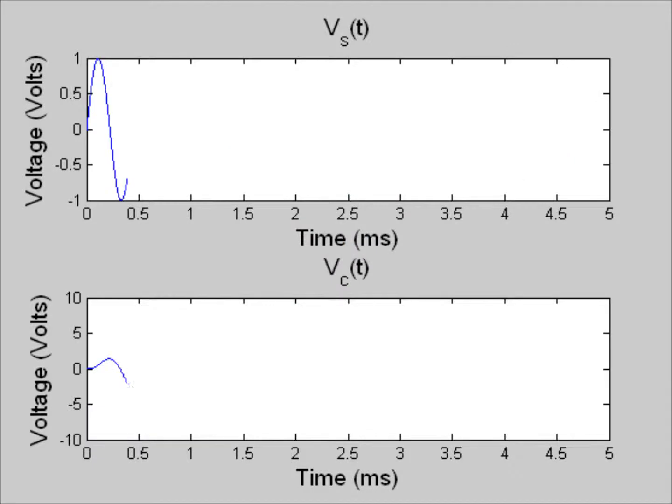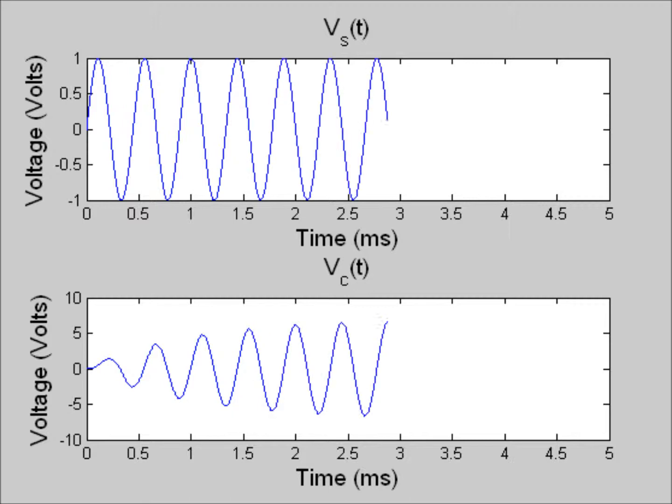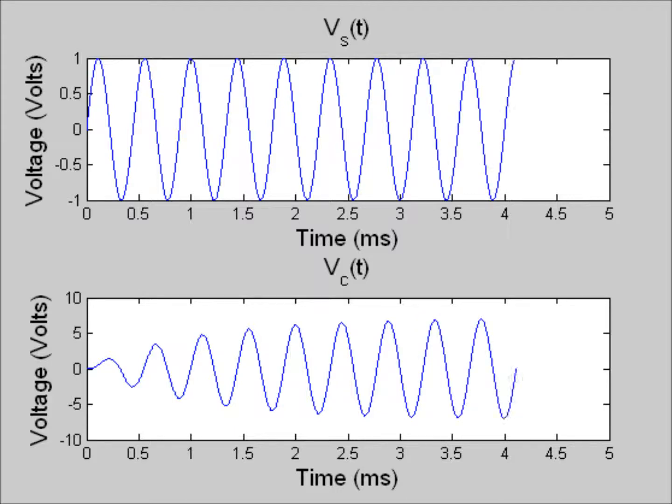So we look at the time domain and we see that the voltage source is adding energy to the system, and it's adding energy to the system at exactly the right time, at exactly the right frequency, to where it's tugging the capacitor voltage along. Note the capacitor voltage is about 7 or 8, the input voltage is about 1. That's the resonance, that's the increase.